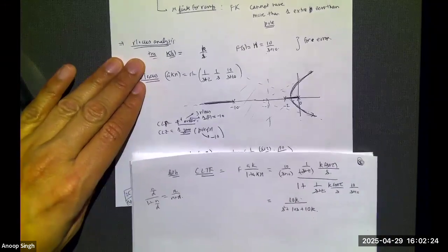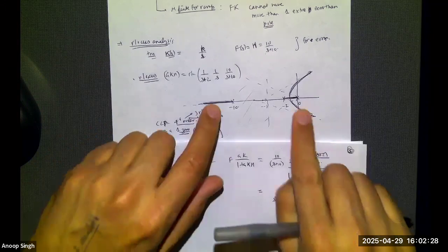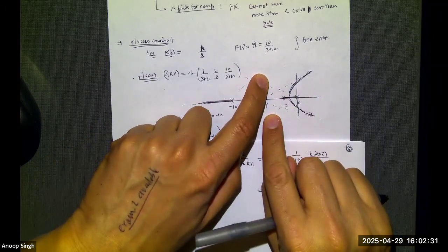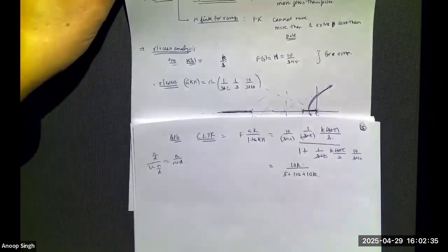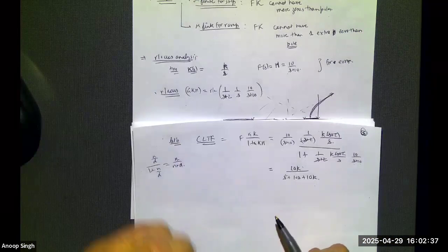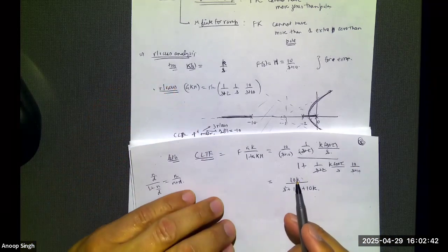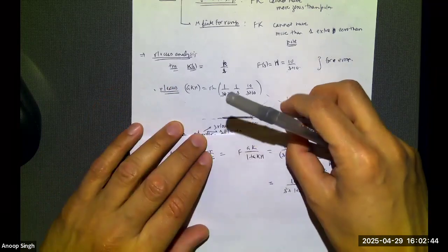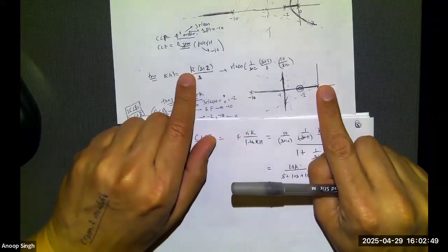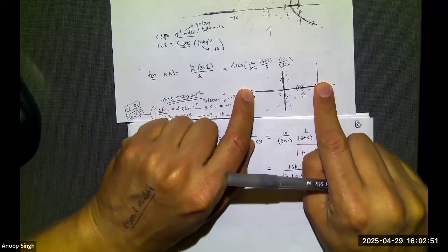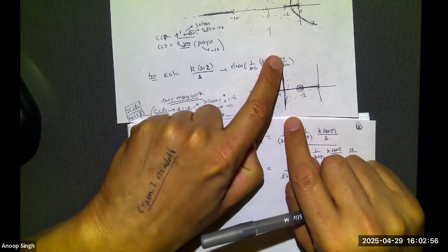If only Jesus can be so kind that when the gain of the controller is 20, I am still within this region. That would be nice. Okay, so how can I check that part? How can I check that when the gain of the controller is 20, I'm not shooting beyond the region? So this is my root locus. When the gain of the controller is 0, I am here. When the gain becomes larger and larger, my closed loop pole is gonna go like this.